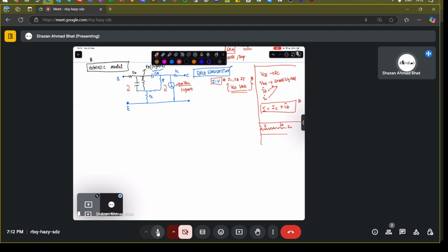One more thing is that whatever voltage is applied here, let's say it's VC, the applied voltage will not be reflected in the circuit. The reflected voltage will be VC dash, which will not be equal to VC. This is the true voltage, and this is the applied voltage. Why? Because there will be a certain voltage drop around the parasitic capacitances, parasitic resistors and other parasitic effects which come into the picture.